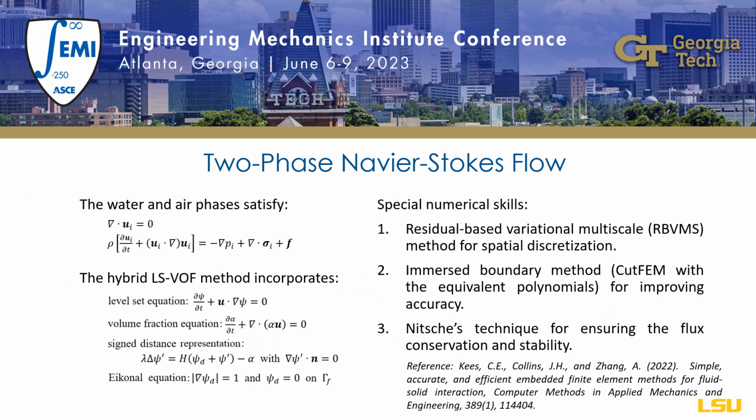In our numerical model, we solve the two-phase Navier-Stokes equations through a hybrid level-set volume-of-fluid scheme. Therefore, a signed distance function should be given to describe the free surface. To incorporate the rigid body dynamics, we have to compute the pressure and the drag on the embedded surface. Several special numerical skills are applied.